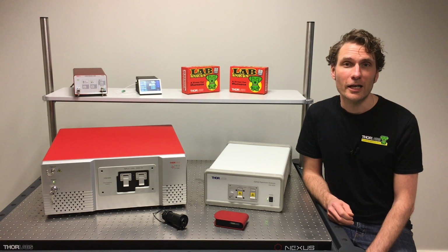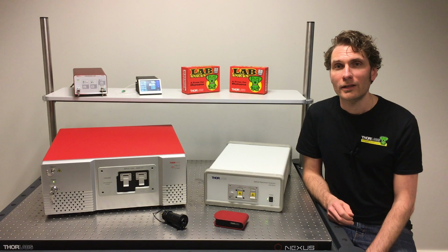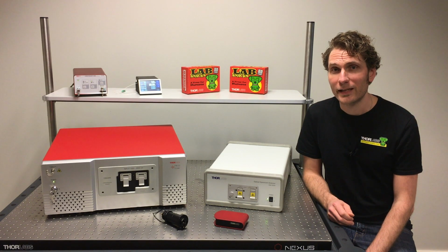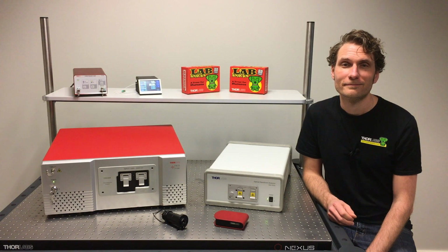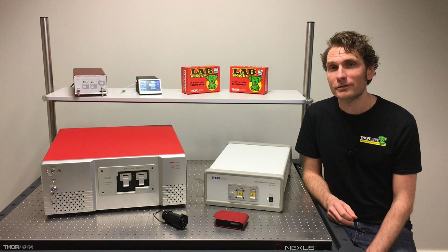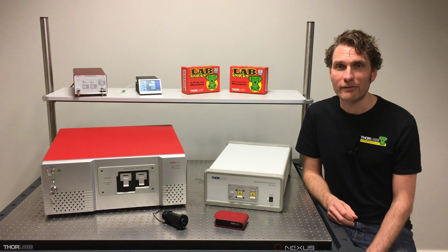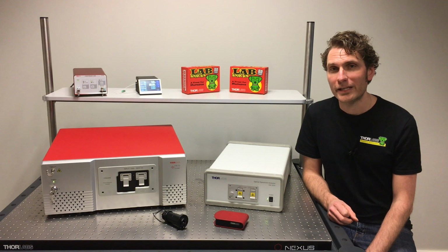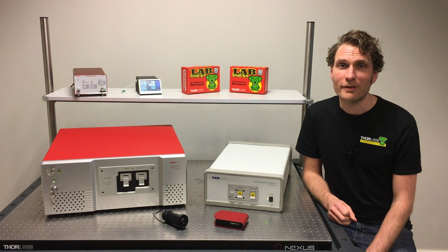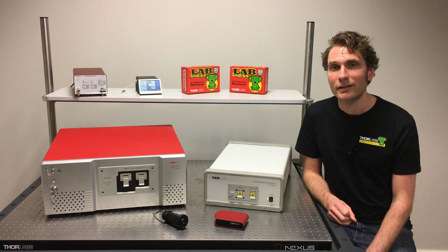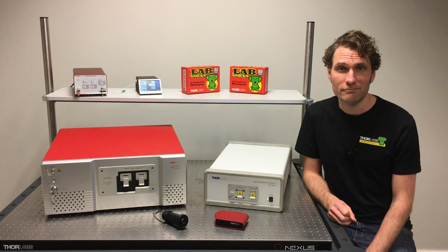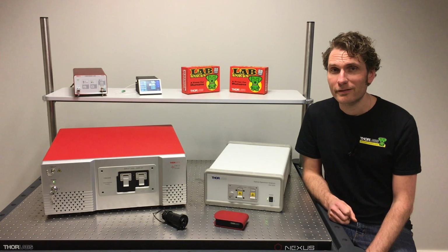The Redstone has an internal broadband reference source, and with this we can determine the accurate location of the center burst. Thus we can average interferograms, which makes the SNR better. And finally, the Redstone gives the user access to its internal reference laser source through the calibration output on the front panel. This reference laser is a DFB laser frequency locked to an acetylene gas cell, and it emits light around 1532 nanometers. The user can do calibration with this laser or do measurements.